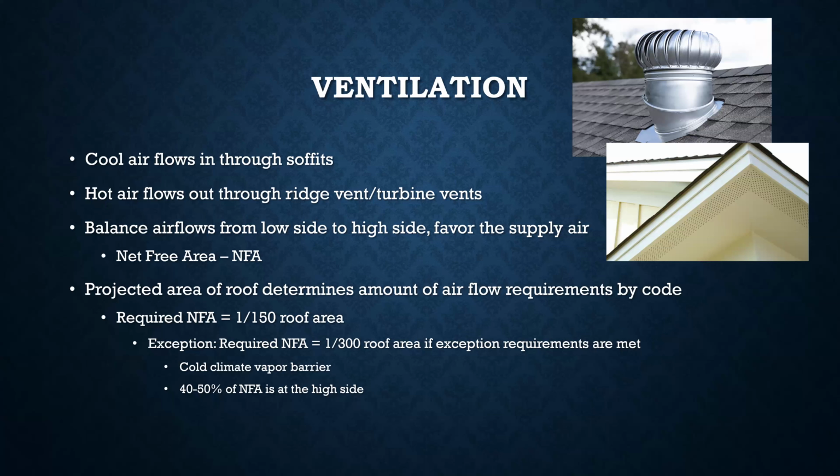Basically, the reason there's a 40 to 50 is you wouldn't want to go like 30/70, because when you go too far, you're not going to ventilate enough, and you're effectively limiting the house. If you have this huge attic and you put a tiny hole in the top and tons of eave vents all the way around your house, your attic is not going to ventilate because the hot air can't get out. But you also don't want to go too much and suck air through your house. So that's why the 40 to 50% range is a happy one.